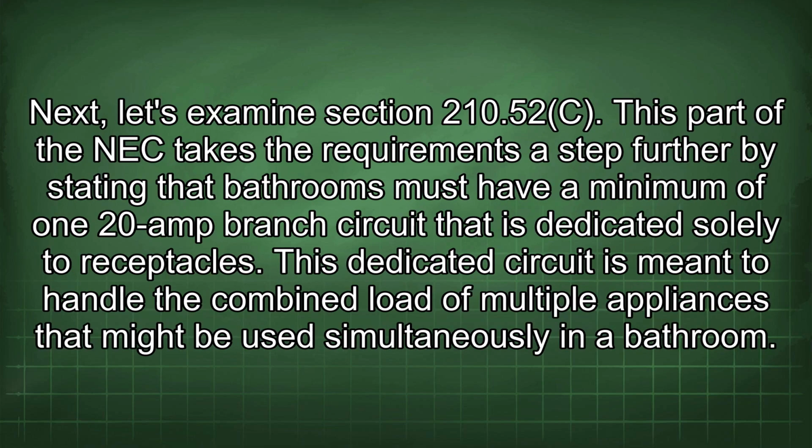Next, let's examine Section 210.52(C). This part of the NEC takes the requirements a step further by stating that bathrooms must have a minimum of one 20-amp branch circuit that is dedicated solely to receptacles. This dedicated circuit is meant to handle the combined load of multiple appliances that might be used simultaneously in a bathroom.